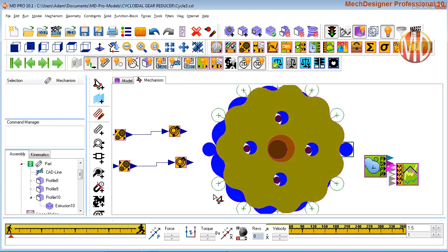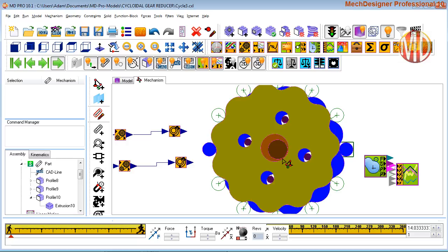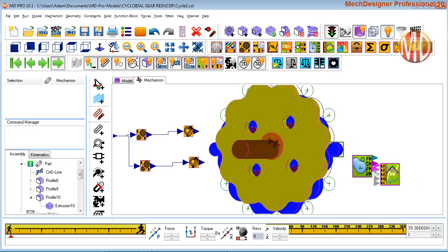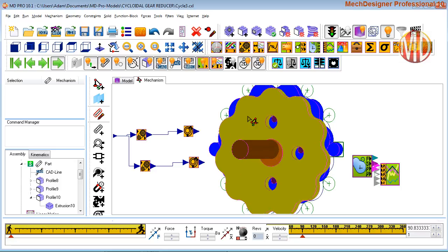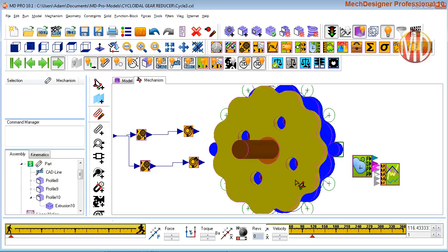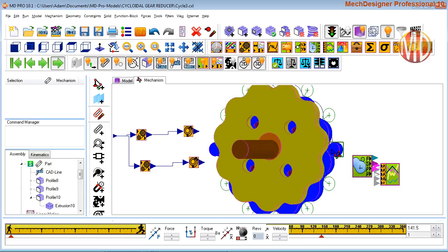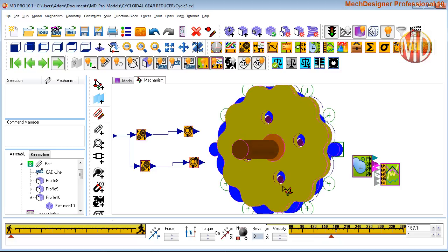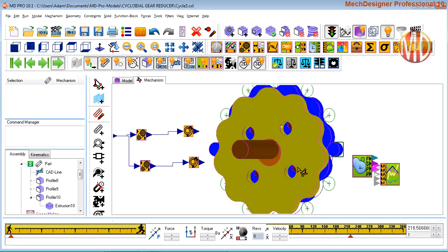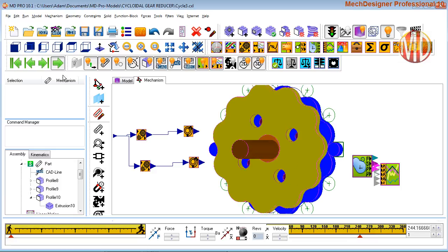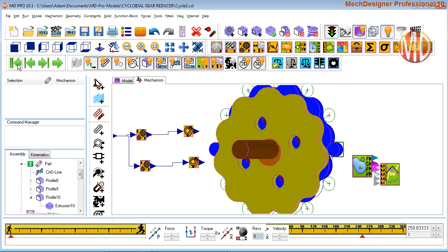So now we have a feel for the rotating input shaft here. So that's rotating, and it has an eccentric disc, which if there were no rollers around the outside, then the disc would just move in an orbit, but because of the engagement with the rollers, it's forced to also cycle itself, and then that motion is imparted to the low speed shaft at the output by engaging with the pins here. So we can improve the layering of that to get the design much better if we wanted to. So next up I'm going to show you how to get the coordinates out for these so we can cut them on a CNC machine.